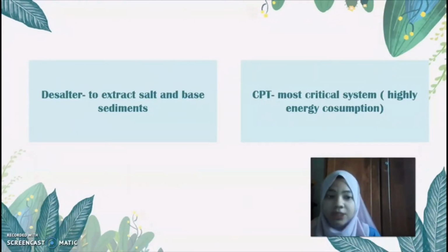The desalter is to extract salt and base sediment, and the crude preheat train is the most critical system, which requires a lot of energy consumption. So to prevent fouling, anti-fouling additives are used.